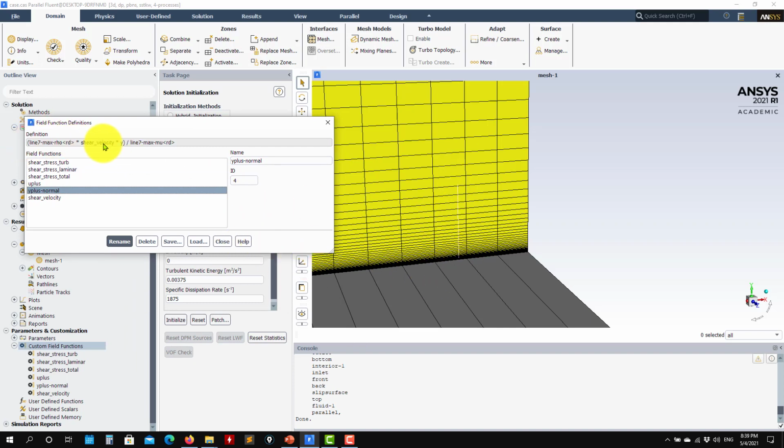So see that we're sampling this shear velocity Y. I know that my coordinate here is 0, so I don't need to do any transformation there. And then divided by mu, and you have it there. Same here for the shear stress. Remember the shear stresses will be responsible for the momentum exchange, for the mixing in the boundary layer. So we have a laminar one that can be computed as strain rate times laminar viscosity, and the other one is strain rate magnitude times the total viscosity, effective viscosity, and strain rate magnitude times turbulent viscosity. So this is how you compute it.